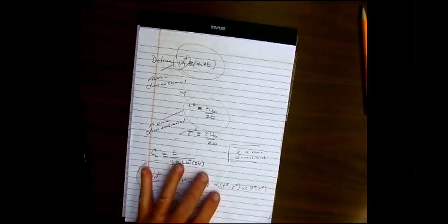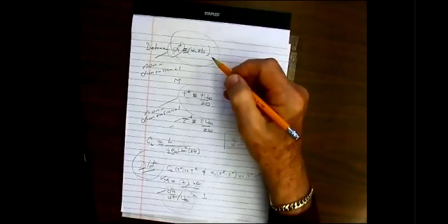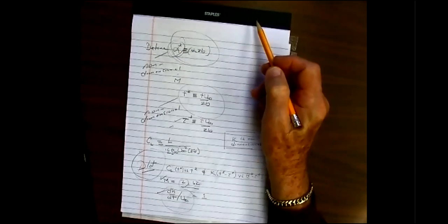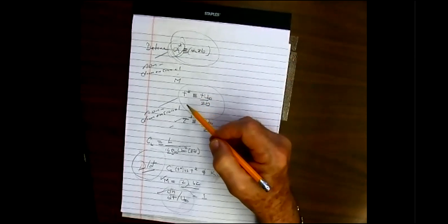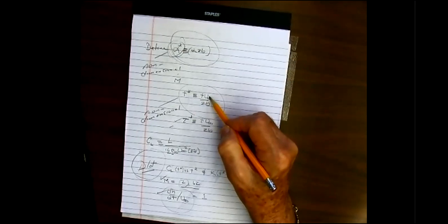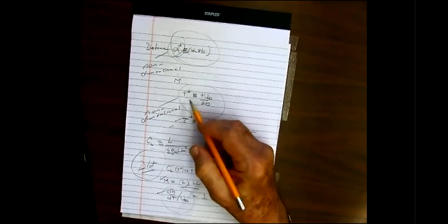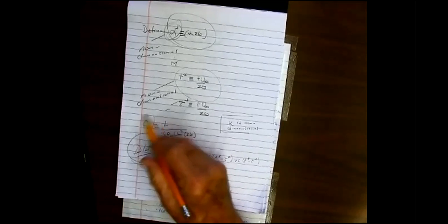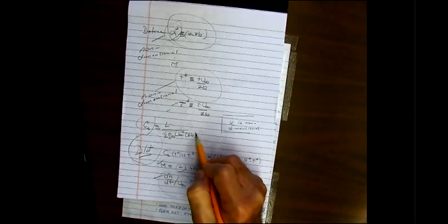Well, as long as I'm here, let me show another page which relates to the homework on Thursday, and then I'll go on to something else. This just tells you what I said in words a moment ago. You wanted to find a non-dimensional alpha equal to alpha times 2b. You wanted to find a non-dimensional time, which is time times u infinity over 2b. And of course, there's a real time and a dummy time, t and tau. And then you wanted to find a non-dimensional lift coefficient, which is the lift divided by 1/2 rho infinity u infinity squared times 2b.